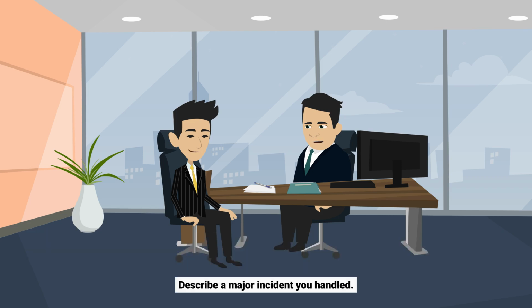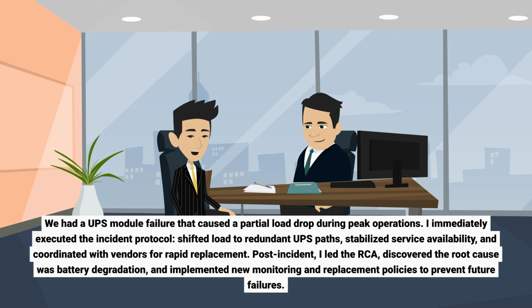Describe a major incident you handled. We had a UPS module failure that caused a partial load drop during peak operations. I immediately executed the incident protocol, shifted load to redundant UPS paths, stabilized service availability, and coordinated with vendors for rapid replacement. Post-incident, I led the RCA, discovered the root cause was battery degradation, and implemented new monitoring and replacement policies to prevent future failures.